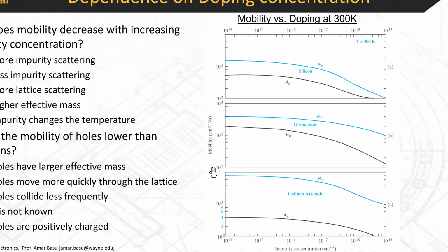All right. So whenever you have high mobility materials, those materials are often useful in high-speed semiconductors. High-speed semiconductors are the ones where you want the electrons to move through the material very rapidly. High mobility results in lower resistances. You can think about circuits as electrons moving through the circuit at a certain velocity. The way circuit designers think about it is that you have resistances and capacitances. So if you have a high mobility material, you're going to have lower resistances everywhere in your semiconductor, right?